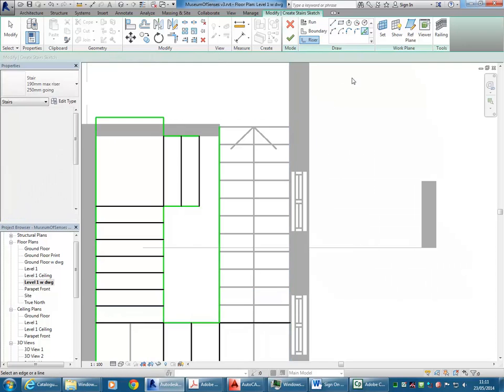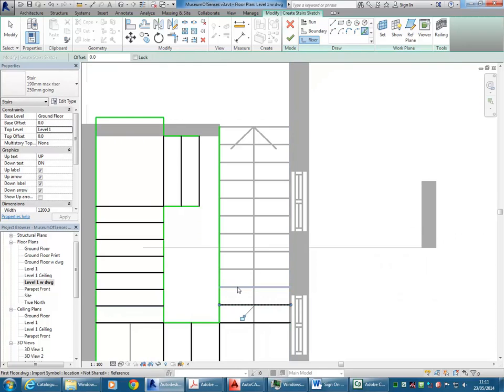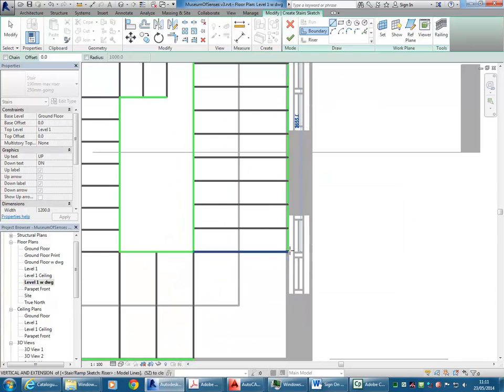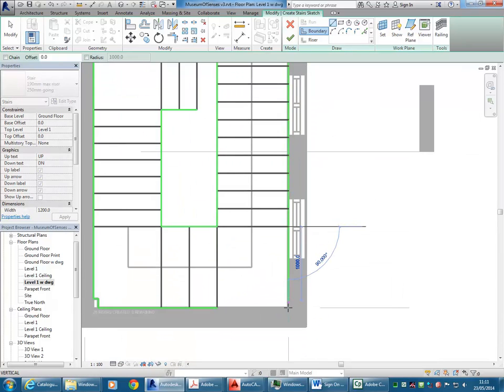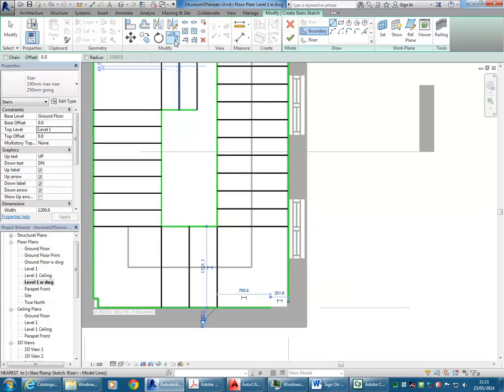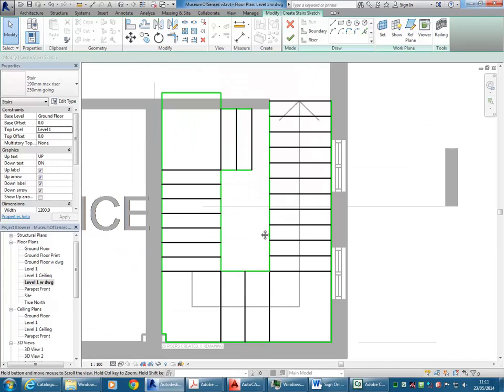Again, I'll just pick line. Do the exterior last. Yeah, you can do it in any order, but probably here that would make sense. And so yeah, okay, so it's being difficult, so I'm just going to take it anywhere that's straight, and then this one I'll do the same thing, just going over to the right, and then with trim, can join it and make sure that I don't have extra lines there. So it's just the two lines on the side, and that's everything I need, I think.